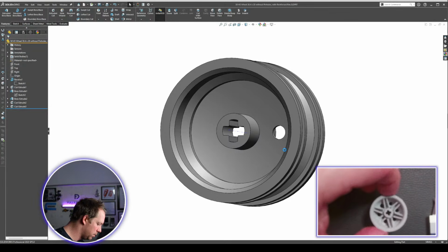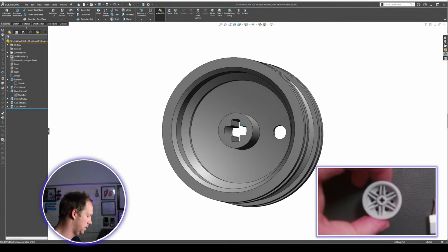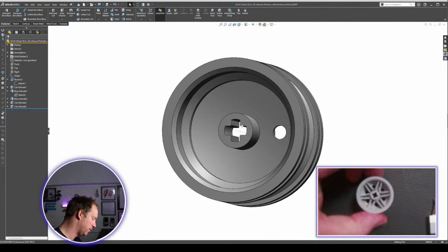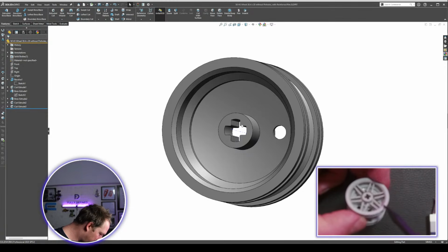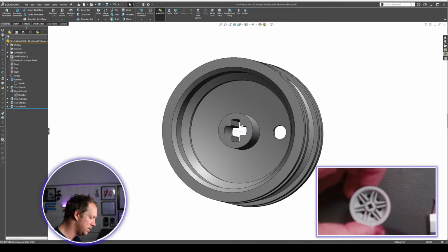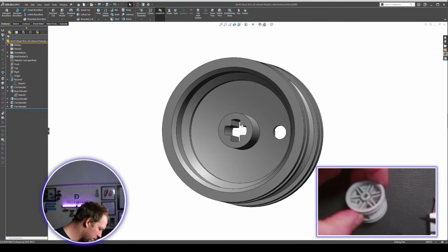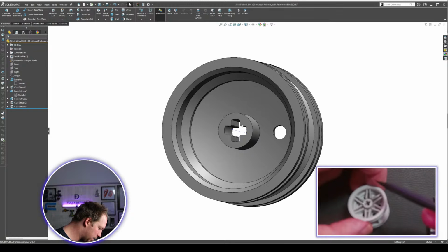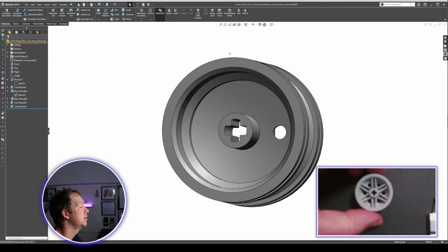We're going to do these 2 ribs. And the interesting thing with those, I said that they've got a curve. It does make it a more complicated part to do because it's not a flat face. If it was flat, I'd sketch on this face and straight down. Because they're curved, I can still do the extra cut afterwards. That might be a good way.